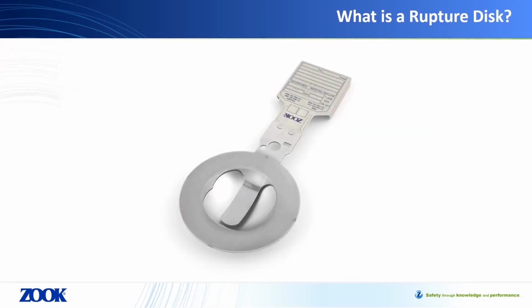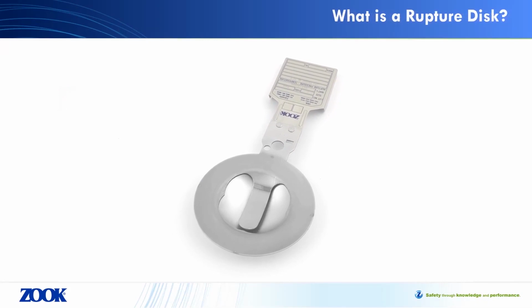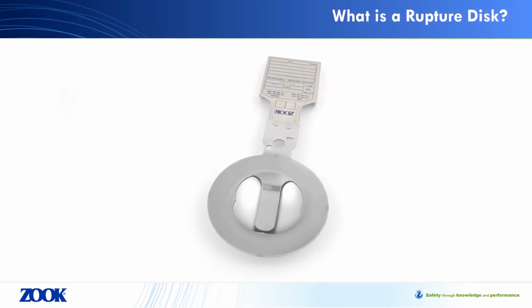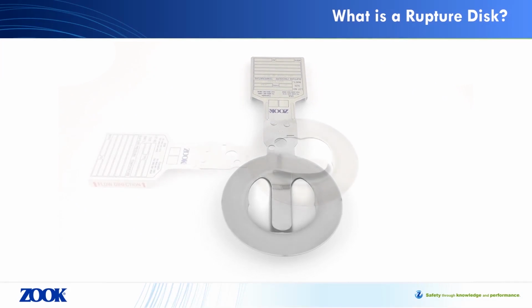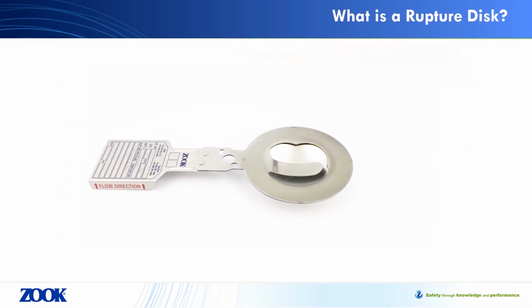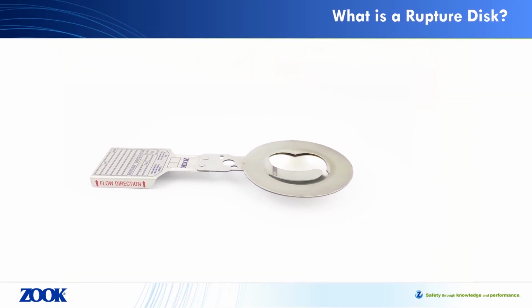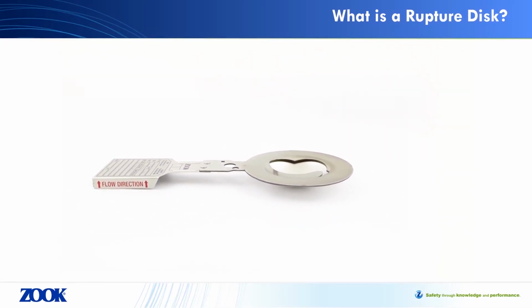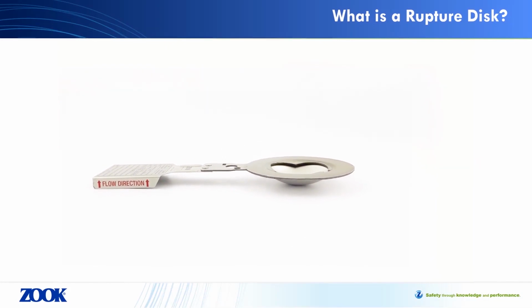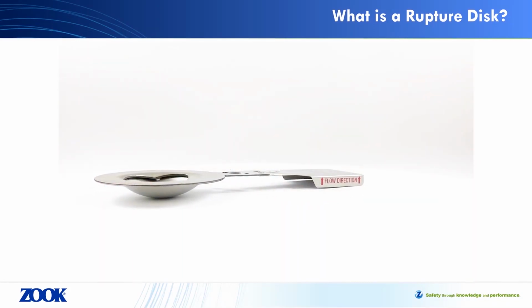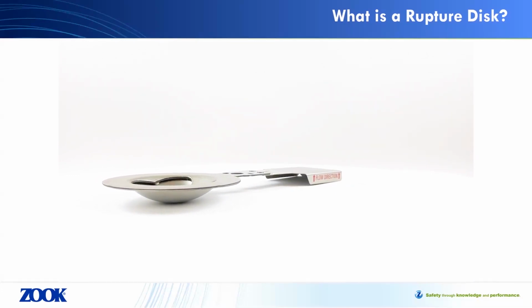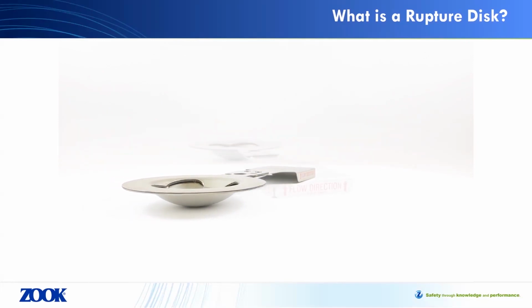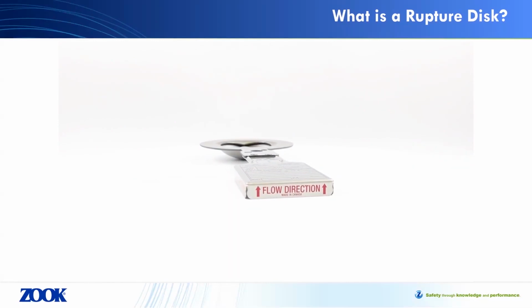Rupture discs are an engineered weak point in a system which prevent things from blowing up in an uncontrolled manner. Unless, of course, you're looking to release pressure instantaneously. More on that later in the discussion. Anytime that we have a system capable of generating enclosed or internal pressure, we have an obligation in industry to ensure that there are safety mechanisms in place to prevent an overpressure event. You may be familiar with other types of pressure relief, such as safety valves. While a rupture disc provides a similar function, there are some similarities and differences. We will cover more details on this later.